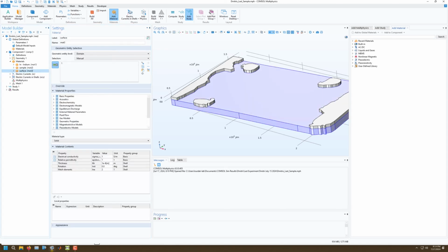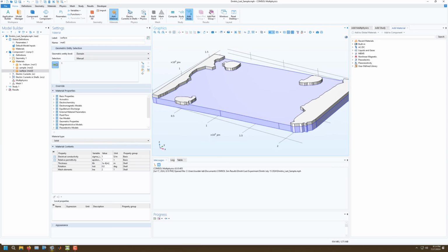So back in the material, this is the layered material that we have. We're going to give it a very small thickness. Let's say 1e-9, 1 nanometer thick. We'll keep everything else for now. And this sample, it has its bulk overridden.